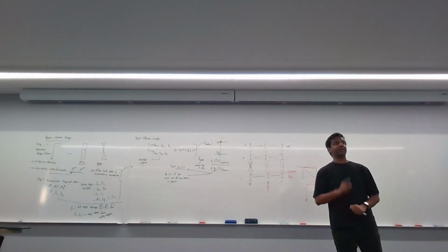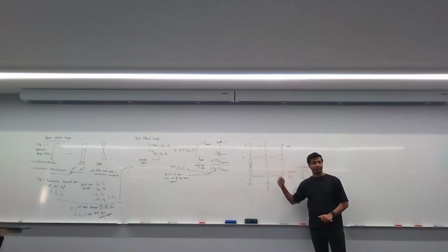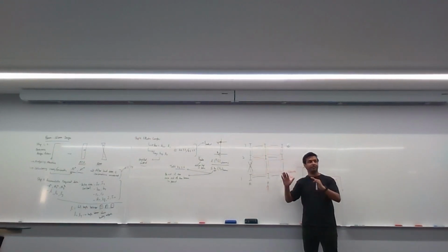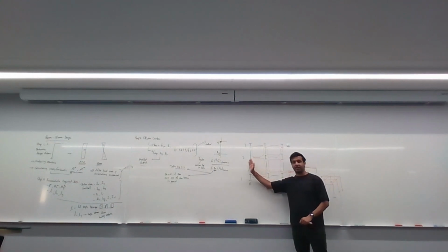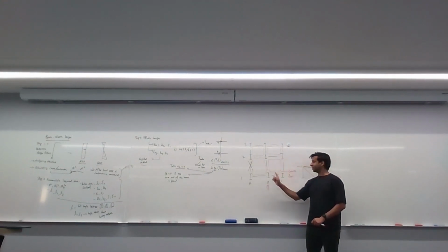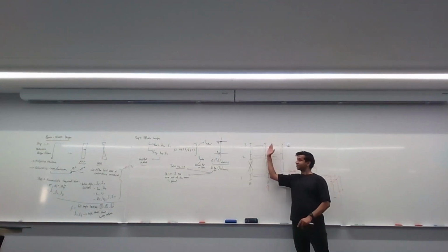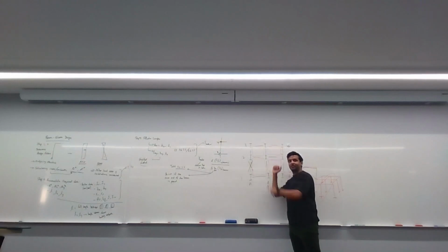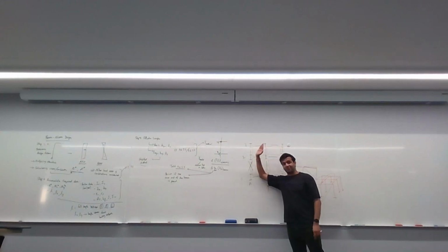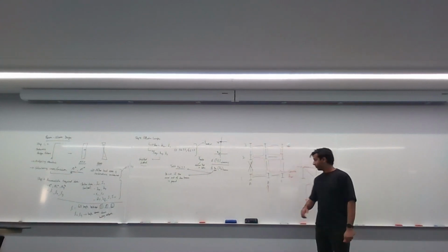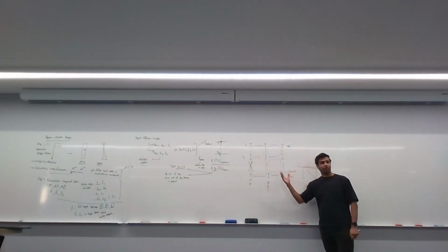That's exactly it. If your floor is stiff enough, if you've got a stiff flooring, you've connected this frame and this frame strictly together. It means that if there's a brace here, this is also braced and this is also going to be braced. Because if you try and push, this frame won't move independently of this. They'll both want to move together. But because this is braced, this will also be braced and this will also be braced. So that is if you've got a concrete floor.